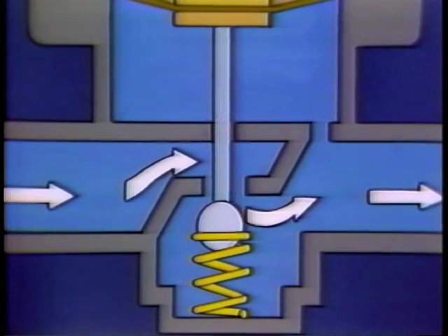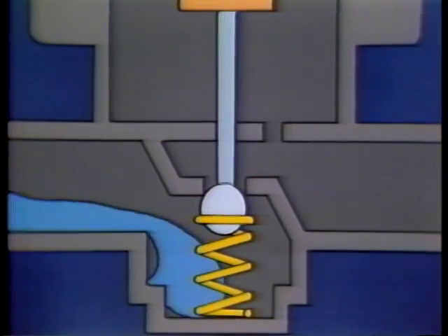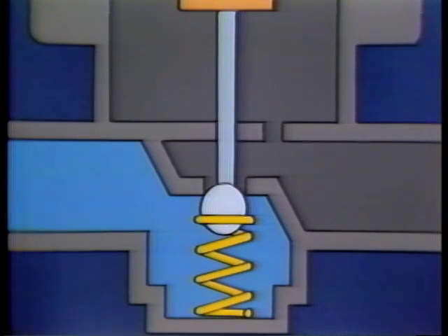It is this pressure imbalance and its effect on fluid as it flows through the valve while it is opening or closing that most limits the use of this design. When the controlled variable is a liquid, the valve must be arranged so that it opens in the direction of flow. Why? If the valve opens against the flow, all of the upstream pressure serves to hold the valve closed.